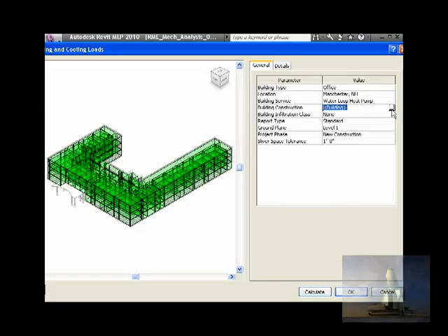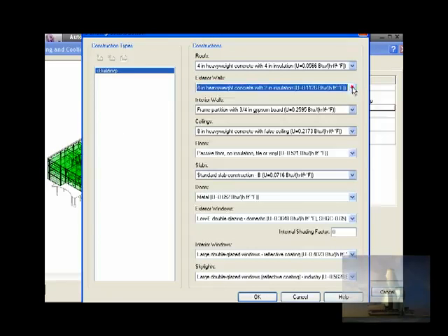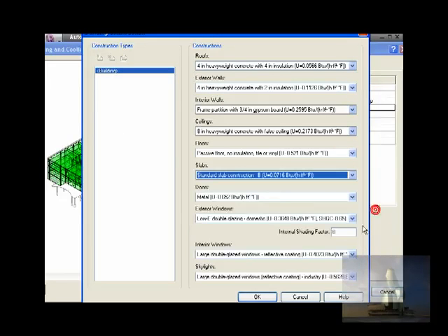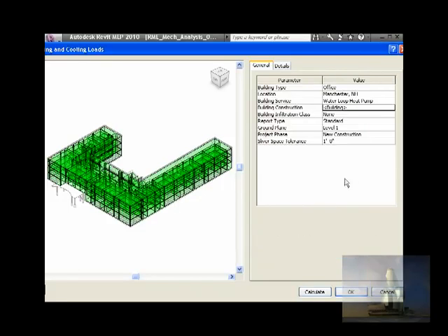So it will say by building, and this is what we did before. I didn't change anything myself, that is supposed to be selected for each project. And building infiltration, I use medium, report type standard, ground level will be level 1, and phase new construction, and space tolerance 1 foot.